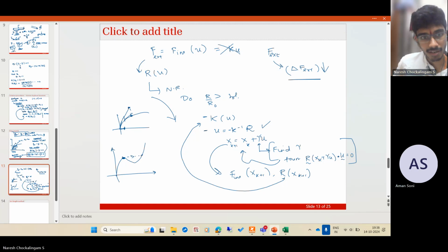So the line search algorithm gets a benefit when you use modified Newton. Instead of using the exact tangent, if you use some approximation to the tangent, in that case line search helps, because in Newton-Raphson, finding the tangent itself is a costly step. Once you have found the tangent, doing another iteration every step will make it extremely costly, and it's not going to help with the computation cost.